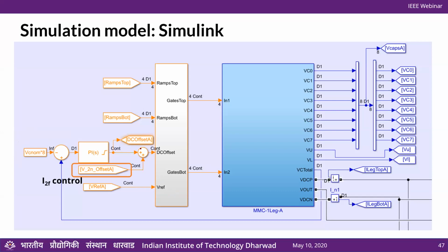The next is this 2F control, which is that DQ controller that I mentioned. Essentially it is just measuring the 3 2F components, determining what should be the offset on 3 phases, and again supplying that to this one. So if you remember, I mentioned that it needs to be added such that the top module gets a positive delta and the bottom module gets a negative delta.